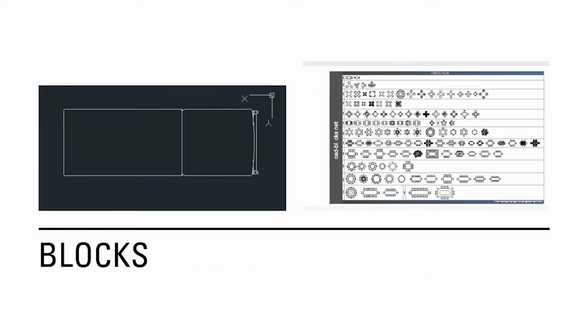Blocks are just figures downloaded into AutoCAD. In my project, we use blocks such as lounge chairs and tables. The image on the right shows where you can get your block from, and the image on the left shows the block in model space. Moving the block to model space is much like copying and pasting in Microsoft Word.